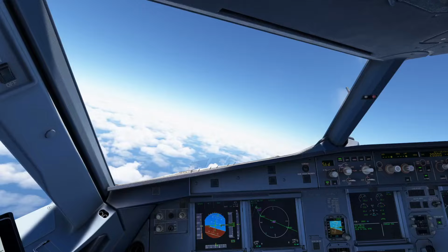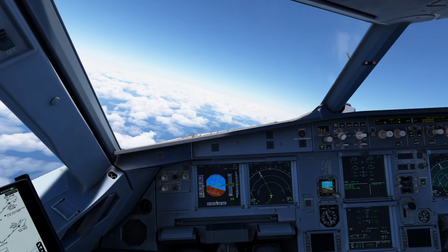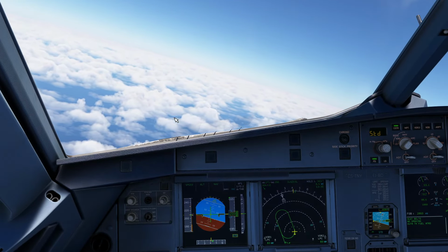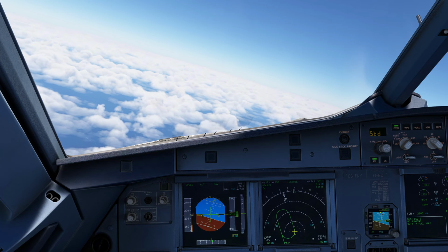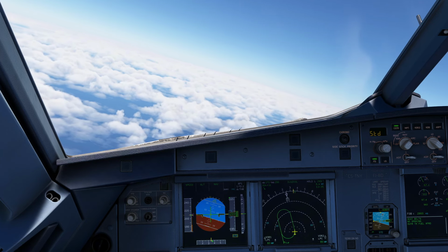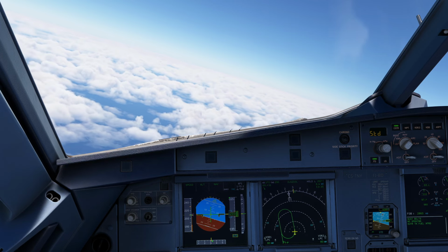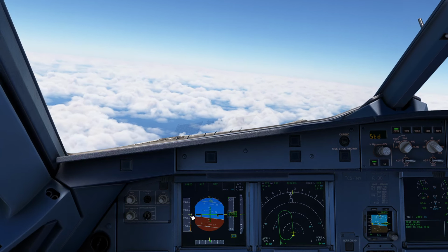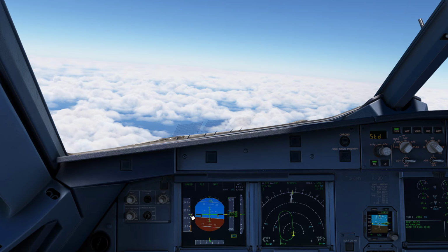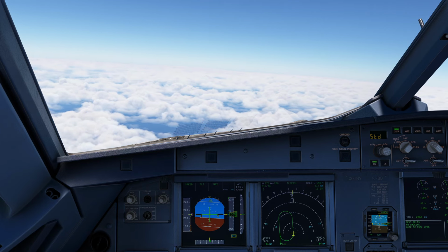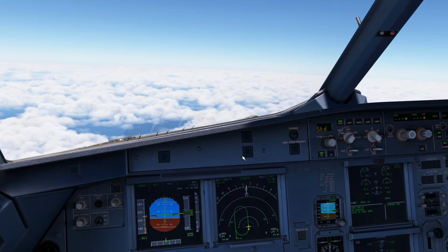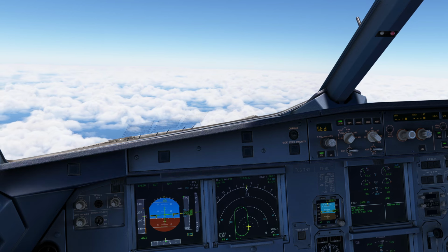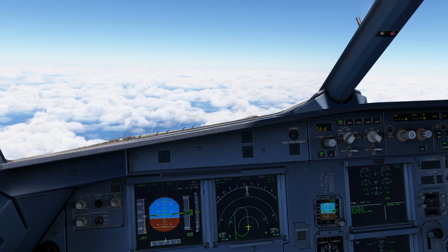And also, if an early deceleration is required just before this pseudo point, what happens? I told you, if the approach phase is activated, the aircraft will decelerate in clean configuration toward the green dot speed. If you select flap 1, it means a slat extension during approach. The aircraft will decelerate automatically to S speed. If you select flap 2, the aircraft will decelerate to F speed.